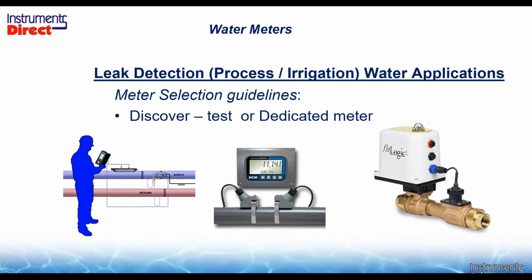In fact, in some cases, by having leak detection equipment, you can actually get better insurance rates on a home or facility if you have the right technology there. So one way to take a look at leak detection, of course, is to monitor flows and see, if you shut off all the valves, you're still getting flow, you've got a leak.